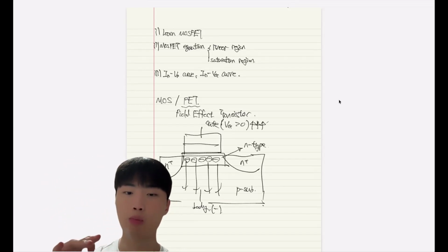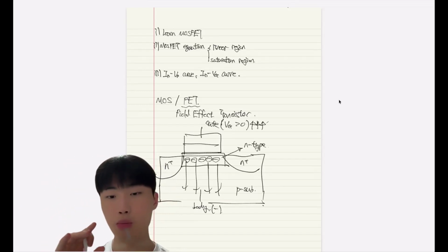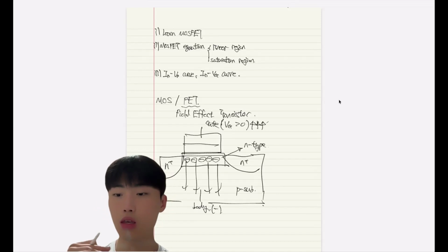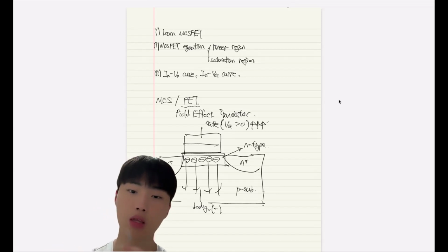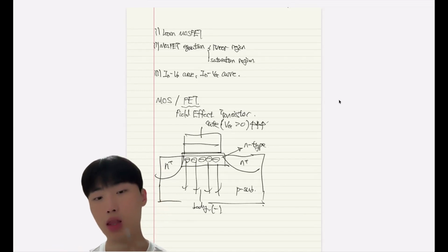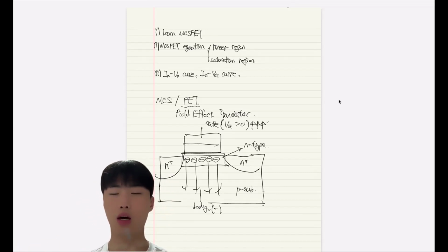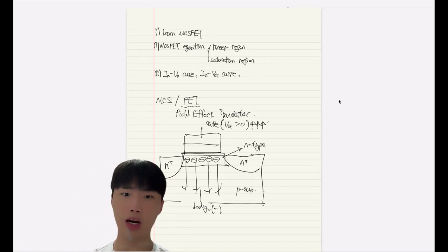That part was actually a P-type semiconductor, but our electrons get accumulated there, so the surface part should be the N-type semiconductor. The energy band diagram shows the strong inversion we learned in the last class.